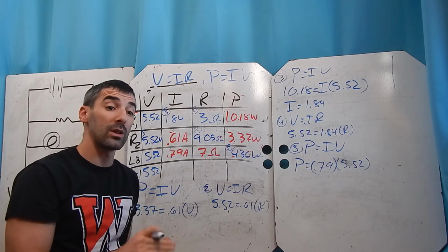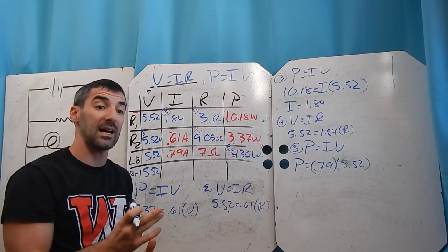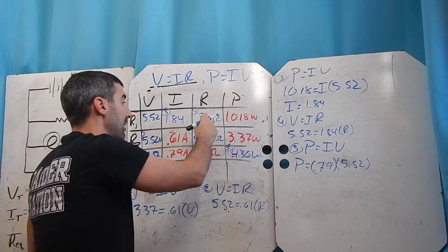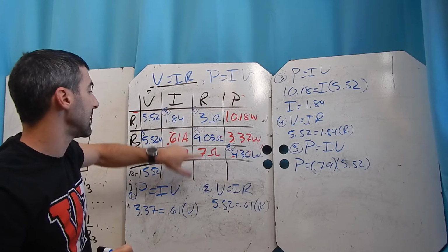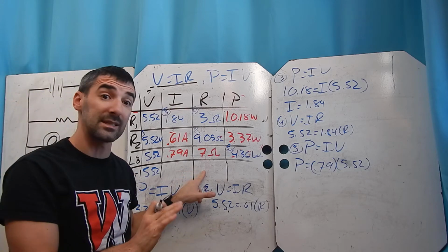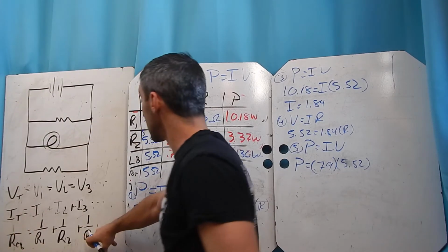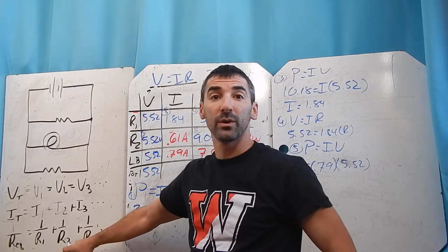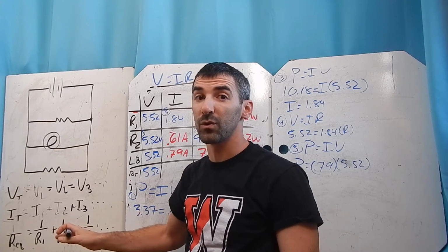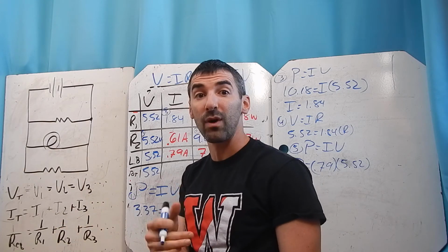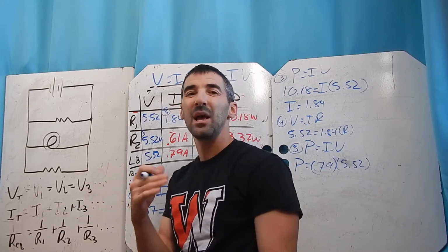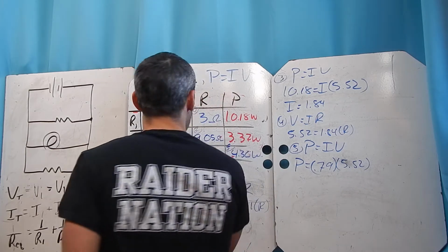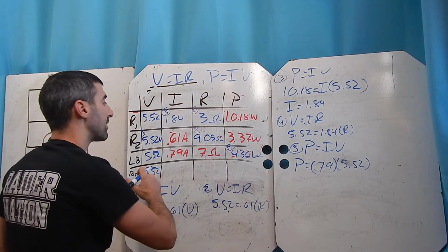And now we're just at this total line. Now, the total line is where I don't want you to make a mistake. A lot of students will go, bam, that plus that is the total. So what is that? 19.05 ohms. That doesn't work here because my resistance rule, 1 over Req equals 1 over R1, that's a funky rule. Now we can do that right away if we want. I'm going to do that. But most of the time, I'm going to say maybe we should avoid that. Maybe there's a way we can figure everything else out.